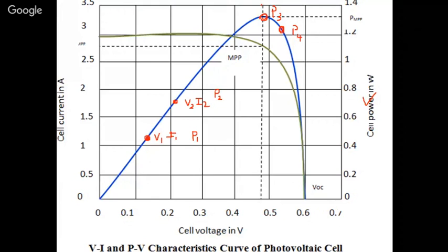So you understood that you have crossed the peak power. So again, you go back to P3 itself. When this slope is 0, you get the maximum power. So that is the algorithm which you have to implement in order to find the maximum power.